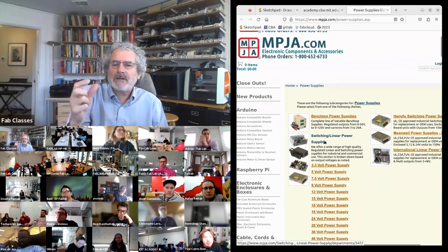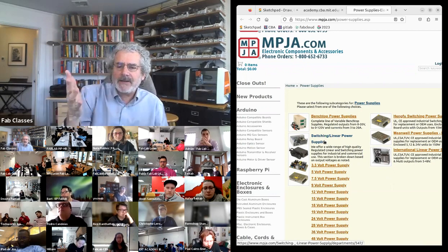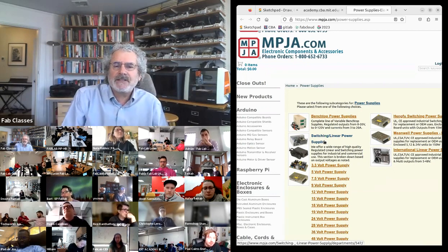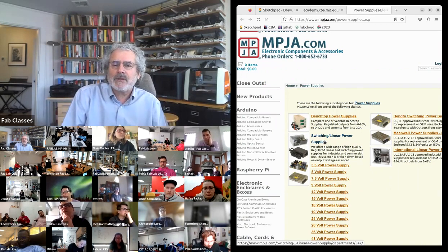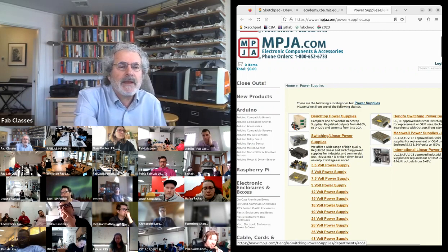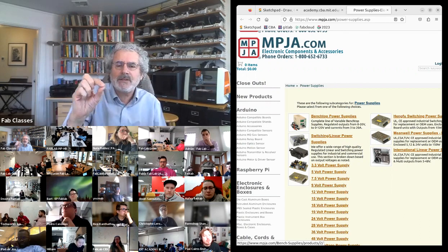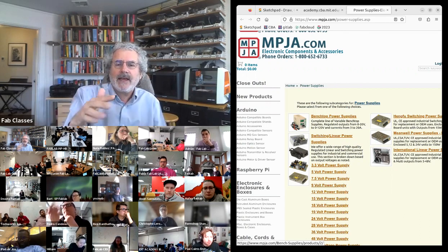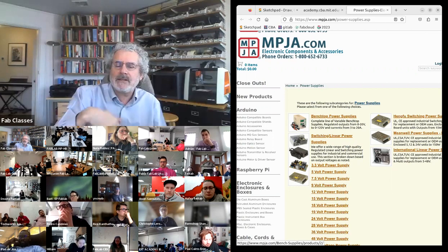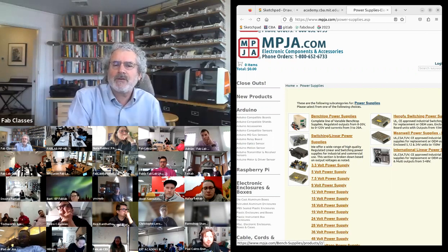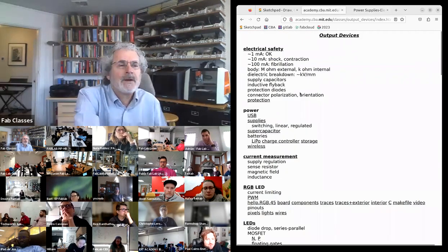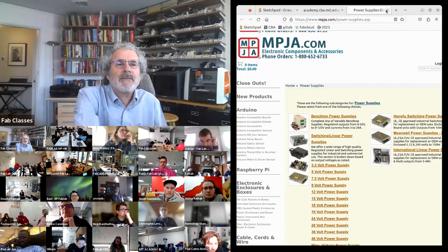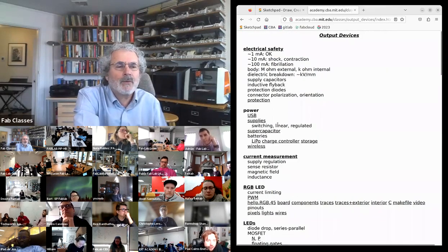Switching ones are electrically noisy, but low cost and fairly efficient. Linear ones are cleaner power, where you need lower electrical noise, but they get hotter and they're more expensive. And the bench supplies like these ones are very useful because they let you separately control voltage and current. If you pick voltage, it'll tell you the current you're using, or if you pick current, it'll tell you the voltage. So those are handy things to have at your workbench.